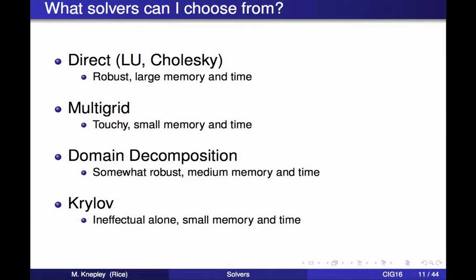There are examples of this in PETSc. They're not general purpose yet. They're specialized. So we don't recommend them for general PyLith use, but we do use one of them as sort of a default solver, the additive Schwartz method, where you just solve in each block and hope for the best. Maybe you'd use some overlap.